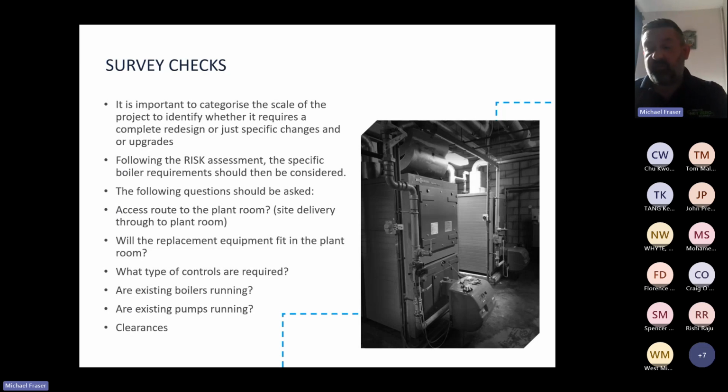Is there an adequate electrical supply to site for the heat pumps, and does, for example, three-phase need introducing? A full heat loss calculation needs to be carried out, as due to the efficiency of heat pumps, it may not be just a case of allowing the same load as the existing boiler load. Is the building insulated correctly, and are improvements required to enable heat pumps to become a more viable option?